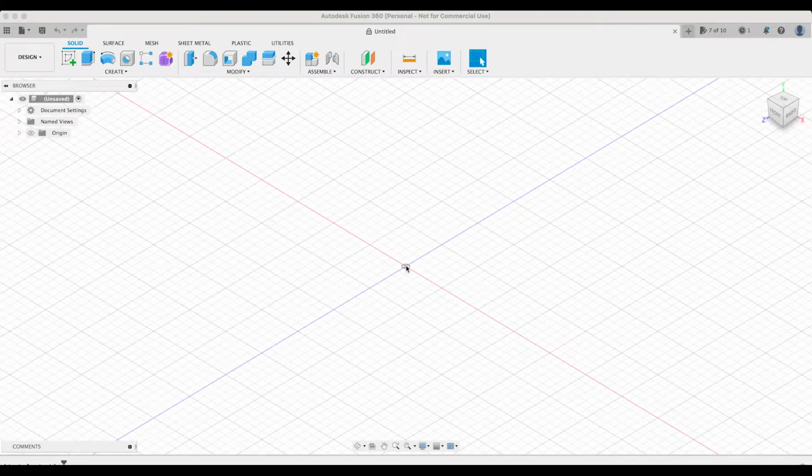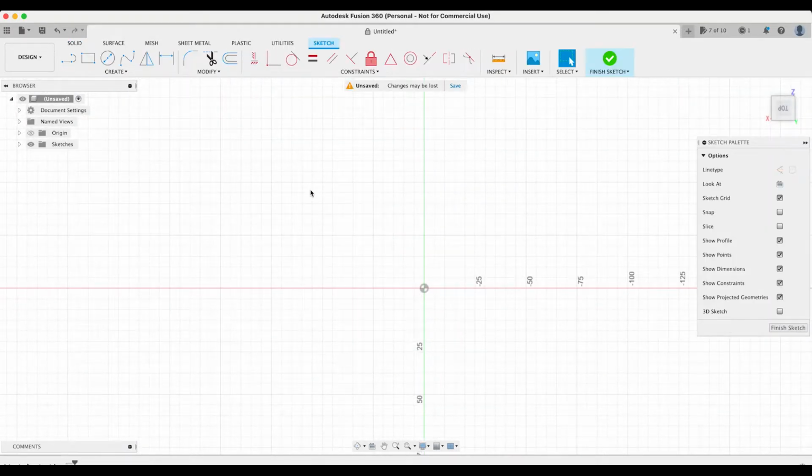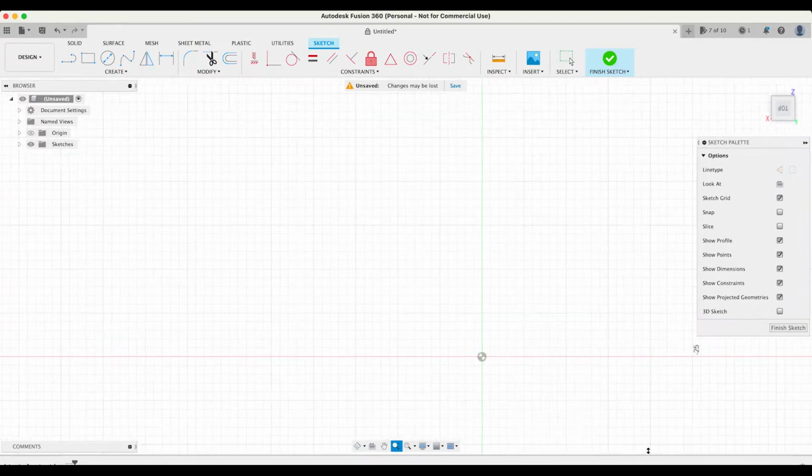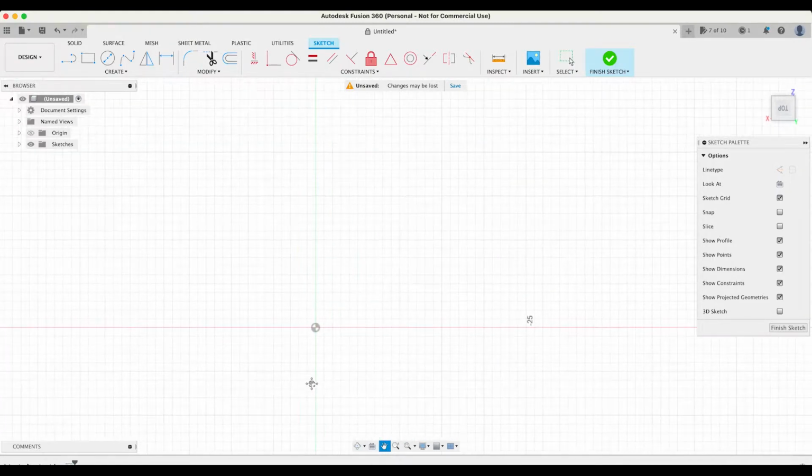In this last Fusion360 tutorial of the current series, we're going to use another tool called the revolve tool. We can use this tool to make a simple profile and turn that into a much more complex shape. So the first thing we're going to do is make a simple profile. We're going to click on the draw tool, select our plane, and I'm going to use the line tool, but I just want to zoom in a little bit so I can use the grid accurately.